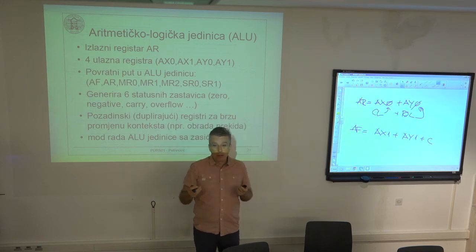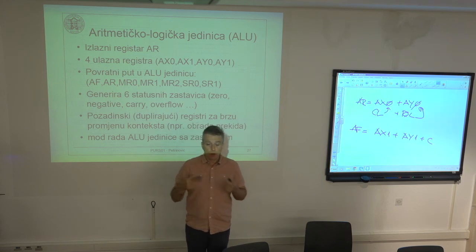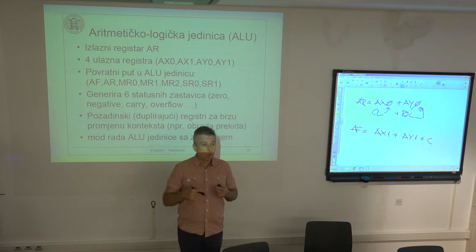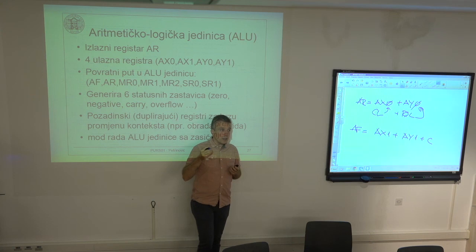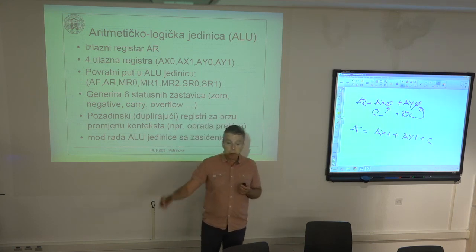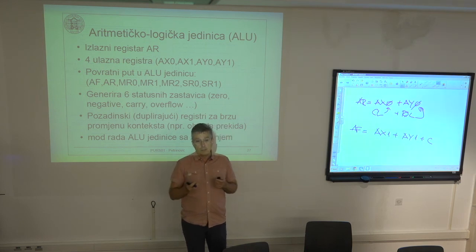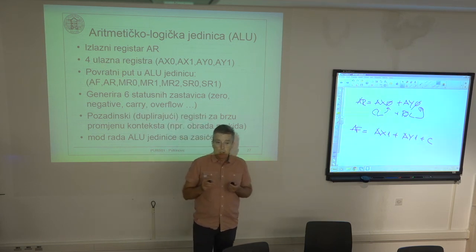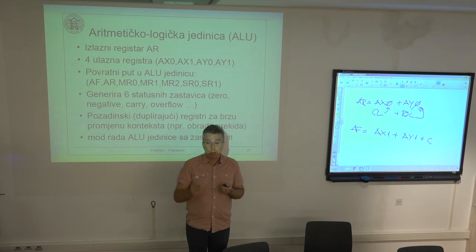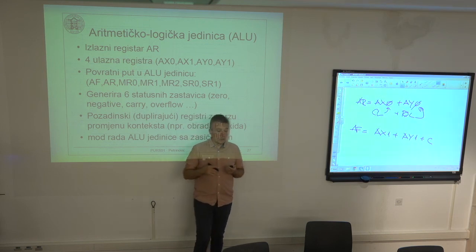Normally, when you have a general purpose microcontroller or CPU, once you service this interrupt, first of all, you have to store the context. So if some register would be destroyed in servicing the interrupt, if you use some internal register on the CPU, the initial value of this register from the main program must be stored. It is stored on the stack. And only then can these registers be used inside this interrupt service request routine. At the end of this routine, the original values are restored in these registers before returning to the main program.